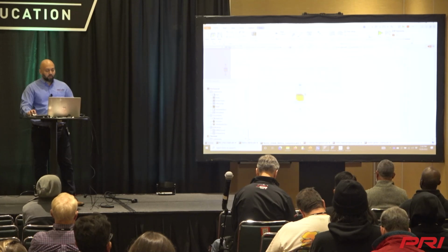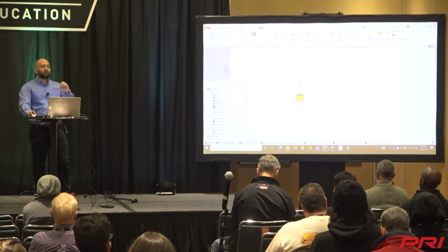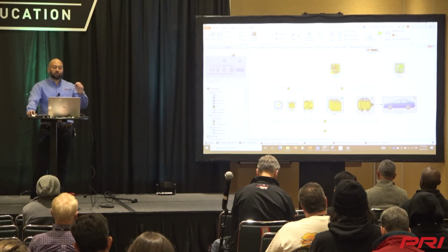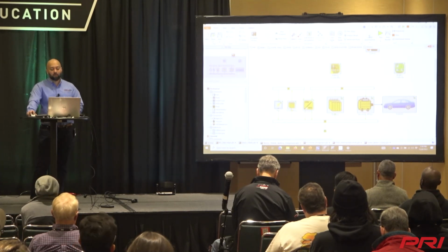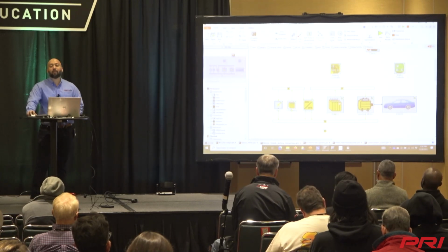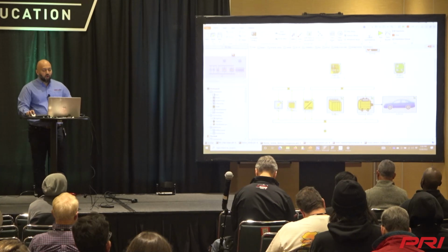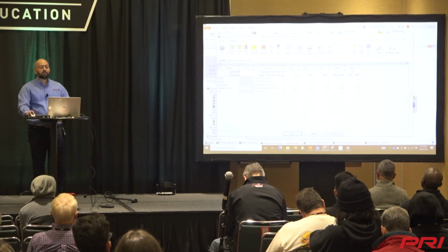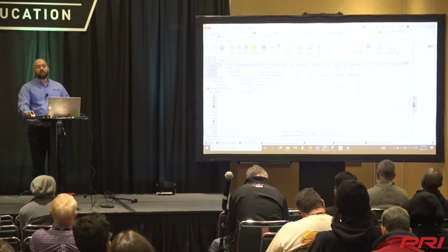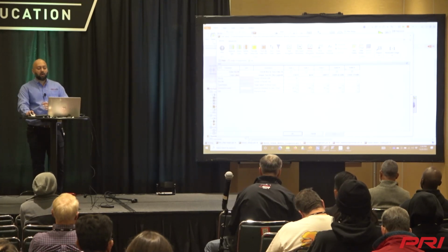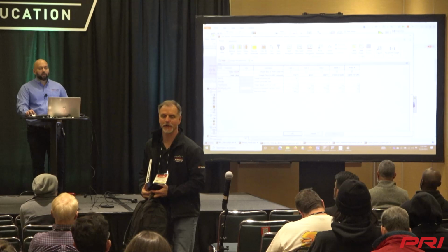All right, so I've gone into different components of this model, and this is the way we set things up. I am skipping a few steps here, like the 12-volt battery, the DC to DC converter, and the inverter, which is taken care of inside the battery element as well. So I'm going to run this simulation. What you're going to see again is a comparison between two battery packs. One is a 50 kilowatt hour battery, the other is the 33 kilowatt hour, and it's going to run an electric truck.